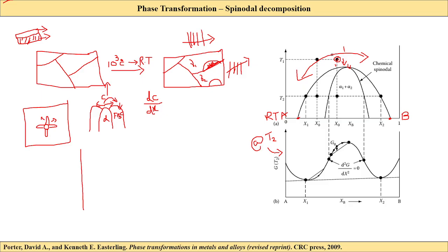We did draw the free energy versus composition for the isomorphous phase diagram, for the eutectic phase diagram, for eutectoid phase diagrams, and peritectic phase diagrams, and even for isomorphous, even for this binodal decomposition or spinodal decomposition diagrams, right? I will clear up the difference between binodal and spinodal in a few minutes. For now, let's see how this is happening. So this whole part, from here to here, these black lines are nothing but the immiscibility gaps.